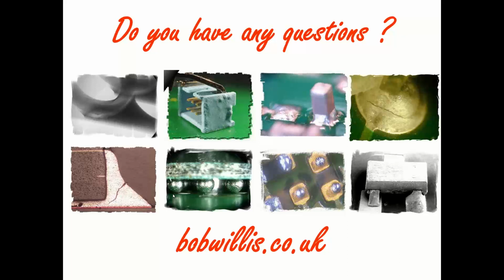So if you've got corrosion underneath a conformal coating, and you've got a bubble, vesiculation, so it's literally bubbling underneath as it reacts because of the voltage across the surface of the part, you've got a chemical trapped within that bubble on the solder resist. What I would want to do is capture some of the fluid inside the bubble and then do some form of analysis on that.